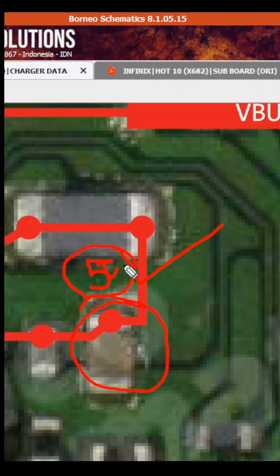There's no need of checking this guy if you see that the voltage is accurate and not fluctuating. It's not going up and down. You see that everything is perfect. It maintains the standard of 5 volts. Okay, all right. So you know that the case on the 5 volts Vbus line, the Vbus relay, has been solved. Okay, that's the perfect point to test.